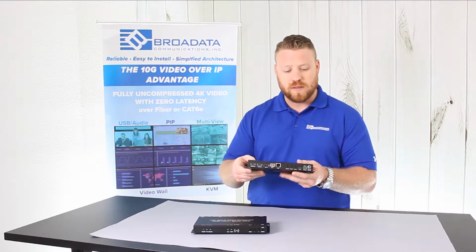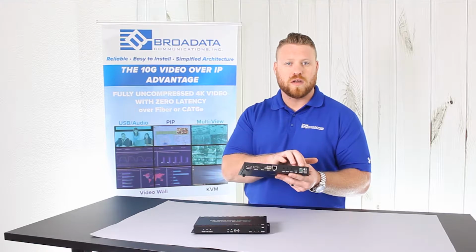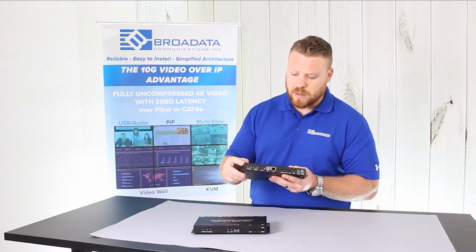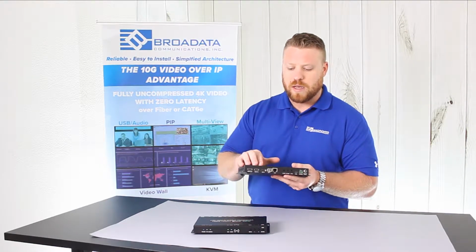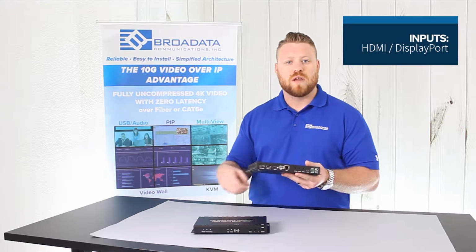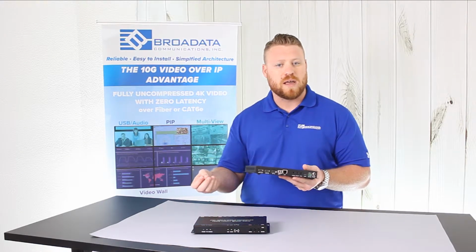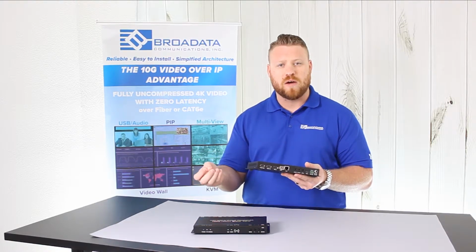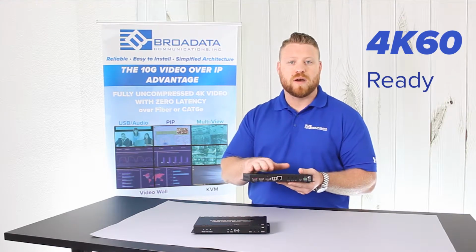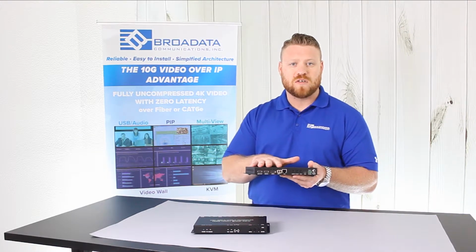And on the back here, you see the various video connections. Because it is fiber optic, it does require additional power unless you're using a fiber optic with a copper cable to power the unit. But we have here on the video side an HDMI input and a display port input. So that helps us solve some problems, not knowing which video input you have, which computer you have. Sometimes they come with HDMI outputs, sometimes they come with display port outputs. And these are 4K 60 ready. Okay, so you don't have to worry about scaling up to 4K 60 or scaling down or compressing that raw data image coming from your sources.